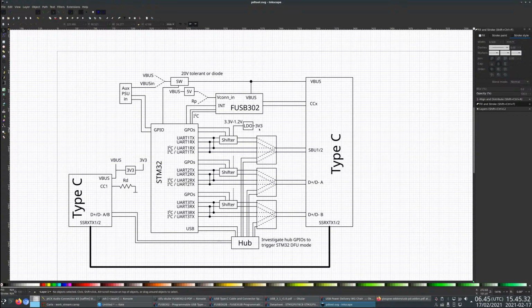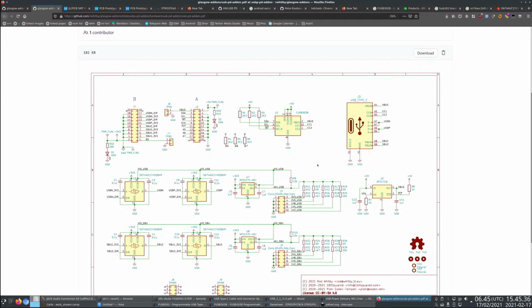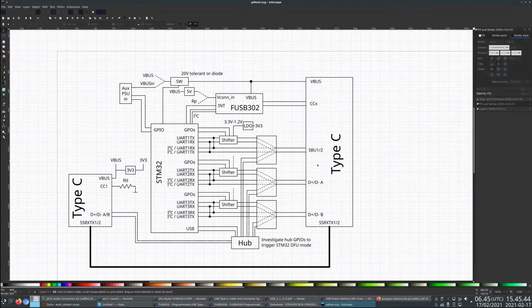I'm assuming we're not going to need two different voltages, like 2.5 or 1.2 or something like that. If you need that, then sorry, you only get to use one of them. But I think that's a reasonable trade-off. The Mac only needs 1.2 and 3.3, and I'm assuming that most of the devices are only going to use one voltage or not have that many options to choose from here. So it just keeps it a little bit simpler.